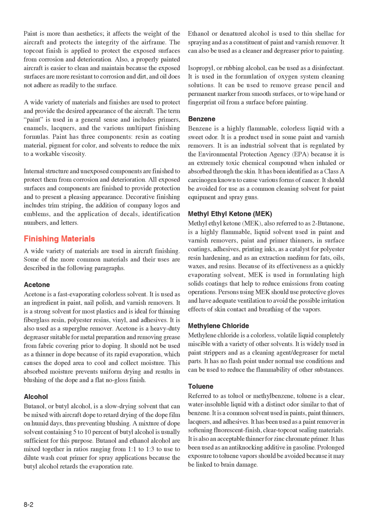Finishing materials. A wide variety of materials are used in aircraft finishing. Some of the more common materials and their uses are described in the following paragraphs. Acetone. Acetone is a fast evaporating colorless solvent. It is used as an ingredient in paint, nail polish, and varnish removers. It is a strong solvent for most plastics and is ideal for thinning fiberglass resin, polyester resins, vinyl, and adhesives. It is also used as a superglue remover.